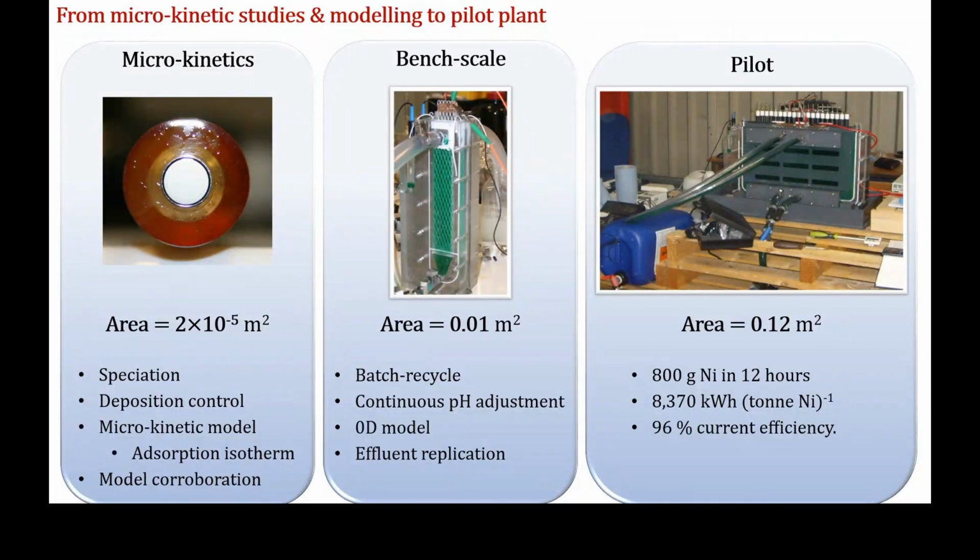And so this involved modeling, a zero-dimensional model, where you model the volume of your electrolyte, how the concentration will decrease with time, what current to apply to make the reduction happen, and how to control the process altogether. So not just looking at reactions for nickel, but all the reactions in the system. And finally, we built a pilot plant, which we tested in Wales.